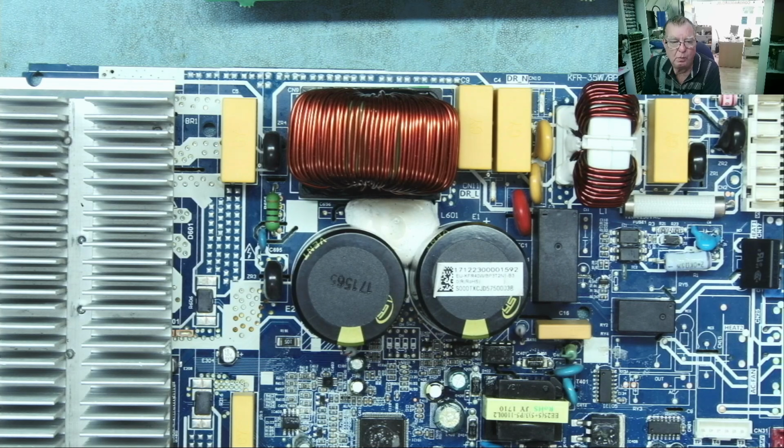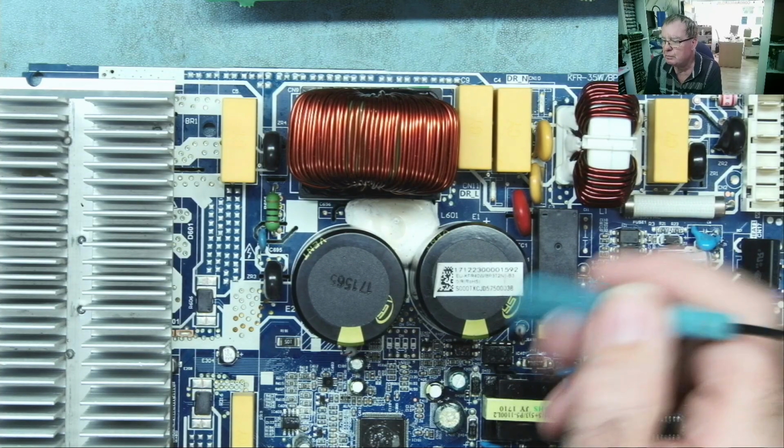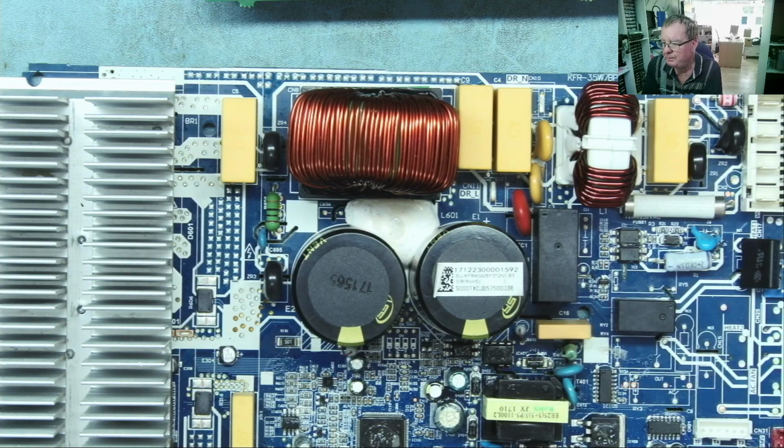Okay, when that glue goes into a dark brown black, it becomes conductive, and conductive means it can short things on the PCB. So any device that you see this old blackened or dark brown glue is a suspect.